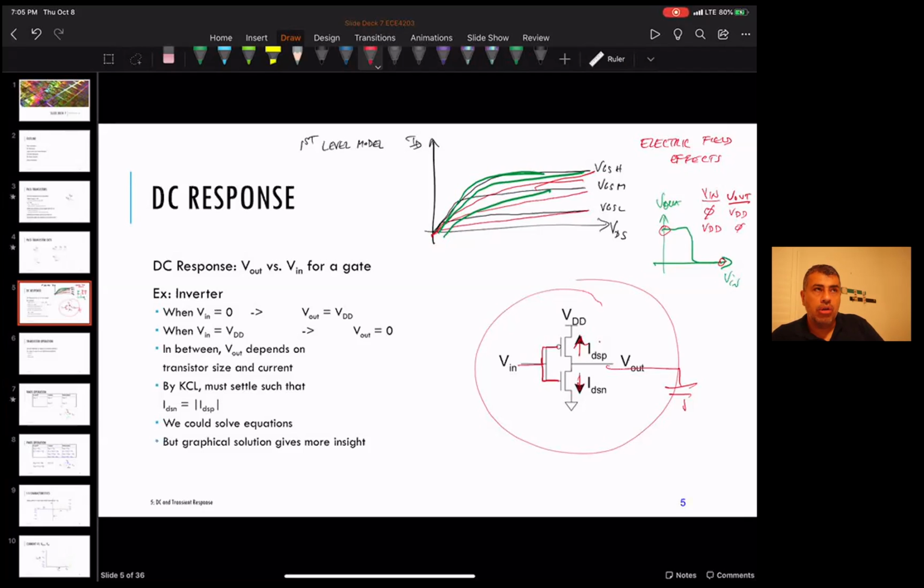They're not all switching at the same time, but even if a small part of those are switching, they're really going to disturb your power supplies. One side of the chip may be switching a lot, pulling the power supply up and down. We'll see in a couple of lectures how much that could really be. It could be a lot. If you have an FPGA, a Xilinx FPGA board or something like that, with some significant amount of switching, it doesn't even have to be that big.